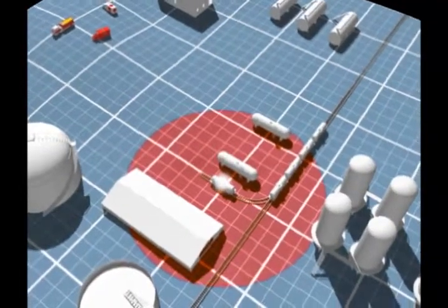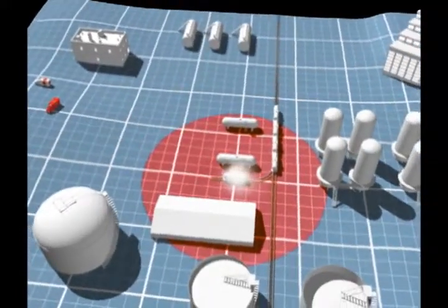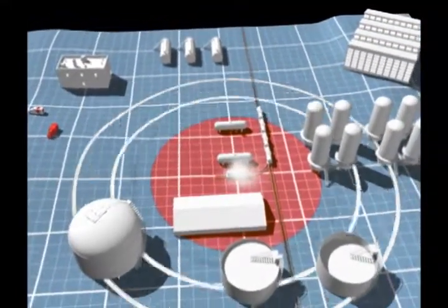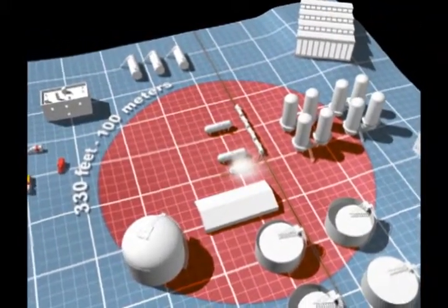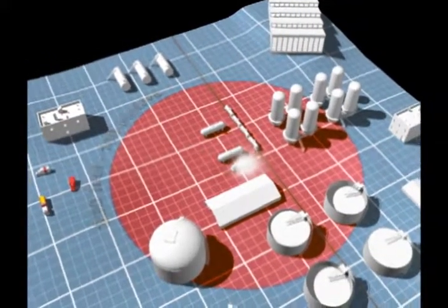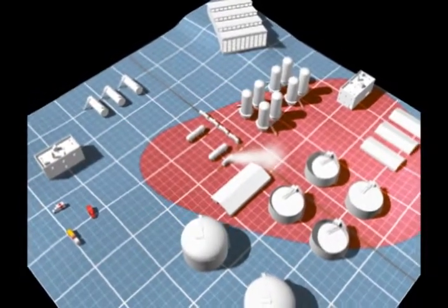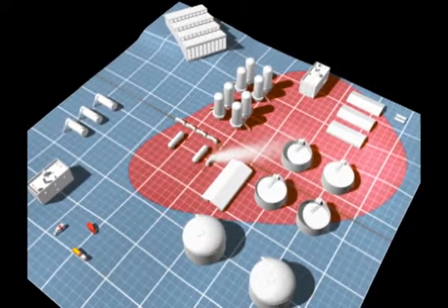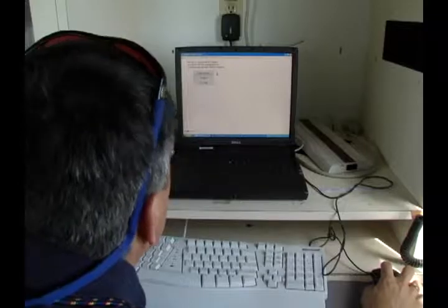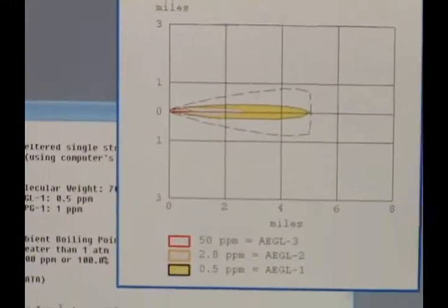The size of the hot zone is influenced by the type and extent of spilled or released material. An MSDS or Emergency Response Guidebook will generally suggest a perimeter of 330 feet or 100 meters for unknown materials. However, if a flowing spill or vapor cloud type incident is occurring, the size and scope of the hot zone will have to be greatly increased. Remember, exact determinations are primarily made by technician-level responders with advanced monitoring equipment and computer-aided programs.